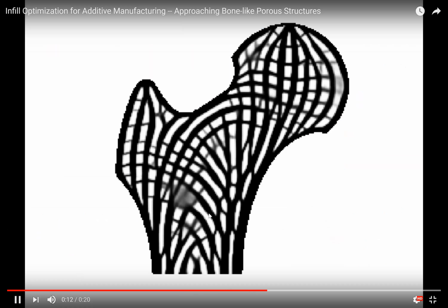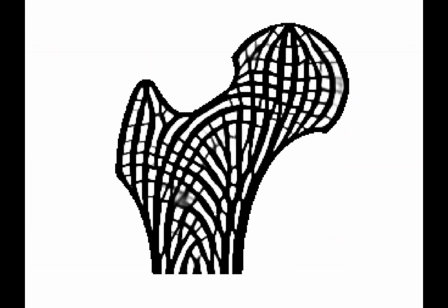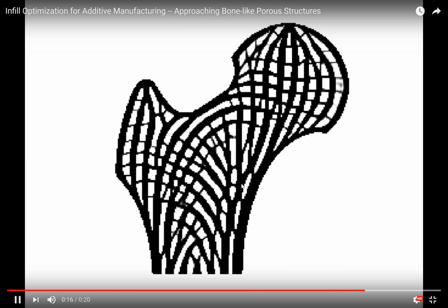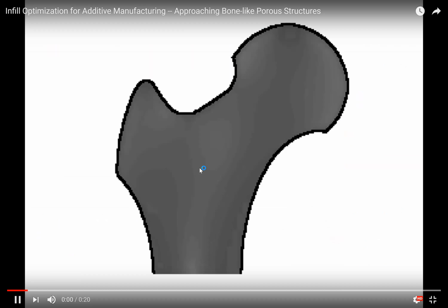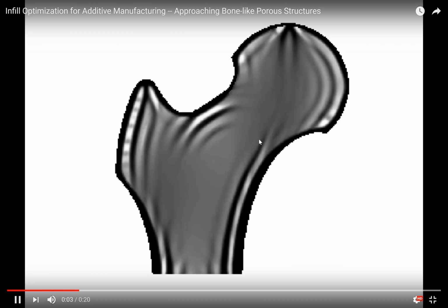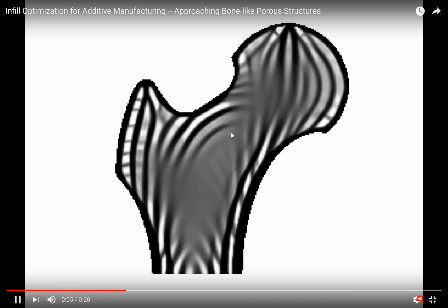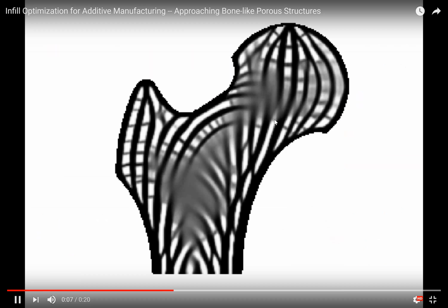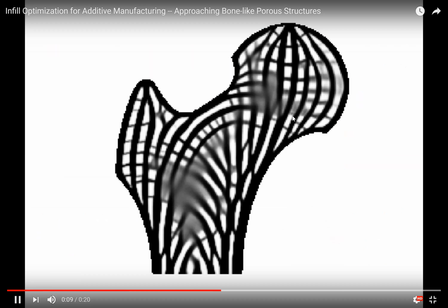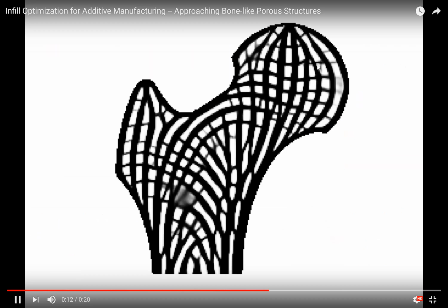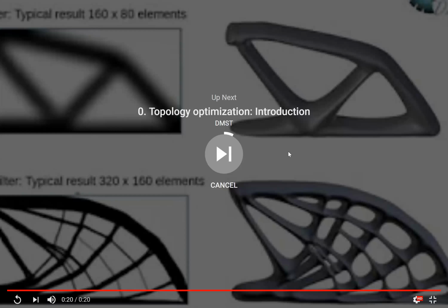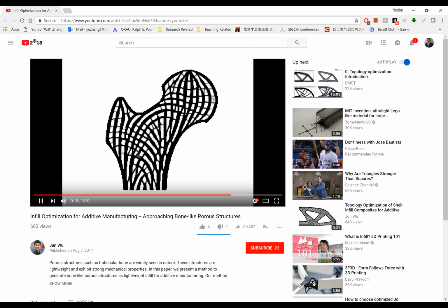So it's a very short video. Basically, it shows how the algorithms optimize the shape. It starts with this basic design domain, and then the topology optimization will automatically generate these infill structures, also with respect to the constraints of the loading and also the volume preserve constraint.